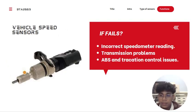So, what happens if these vehicle speed sensors fail? If a vehicle speed sensor fails, it can lead to inaccurate speedometer readings, transmission shifting issues, ABS malfunction, and erratic behavior of the cruise control system. Timely detection and replacement of faulty vehicle speed sensors are essential to ensure safe and efficient vehicle operation.